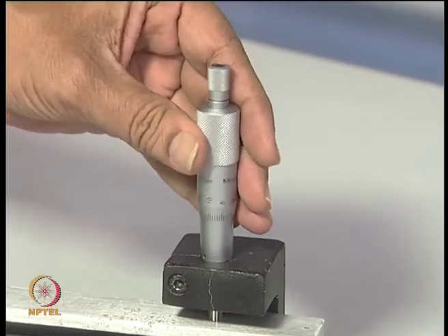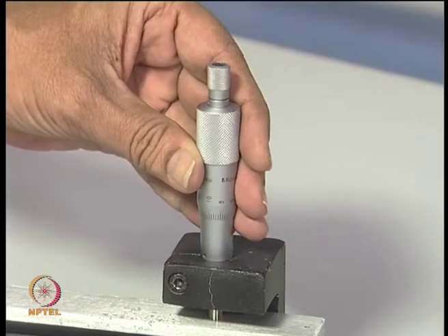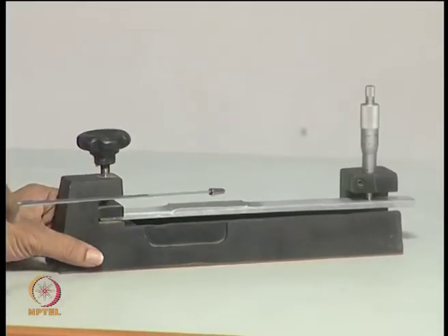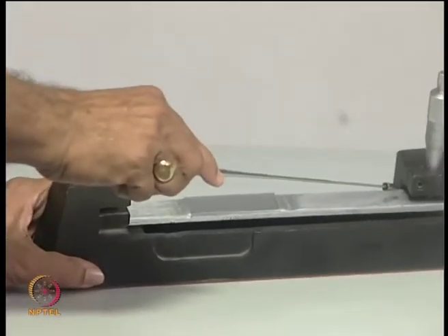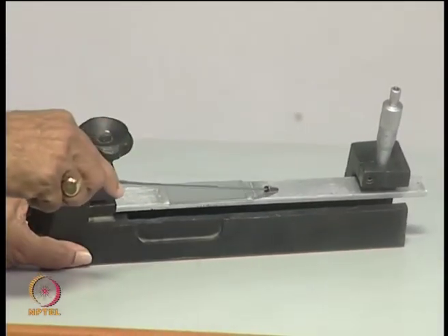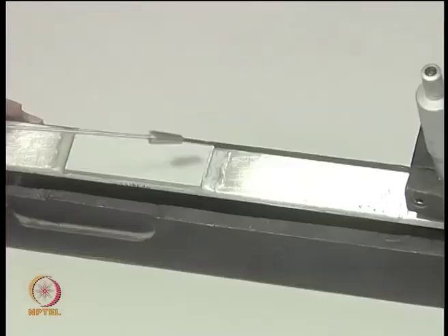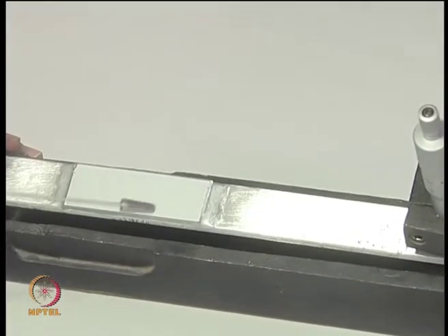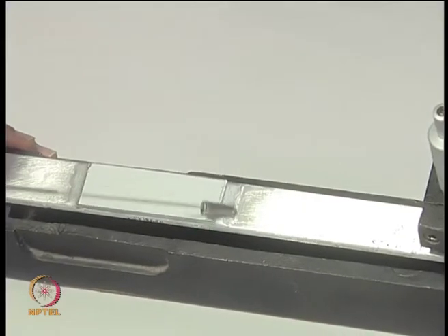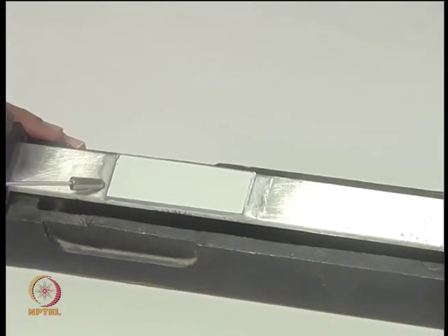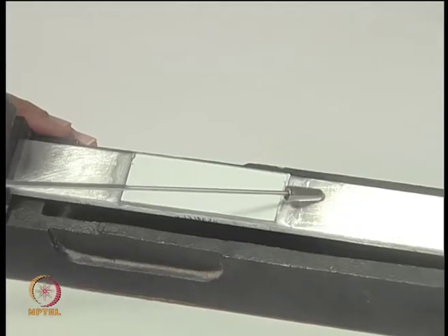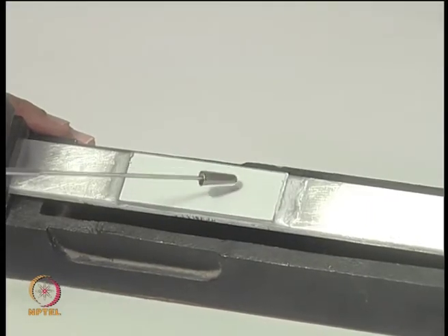You can also note down the level of displacement that is introduced. I have the specimen tilted for your benefit to show that you have a coating pasted, and you can also notice that on either side the glue is applied in a manner that gives a beveled edge for smooth transfer of strain from the specimen to the coating.